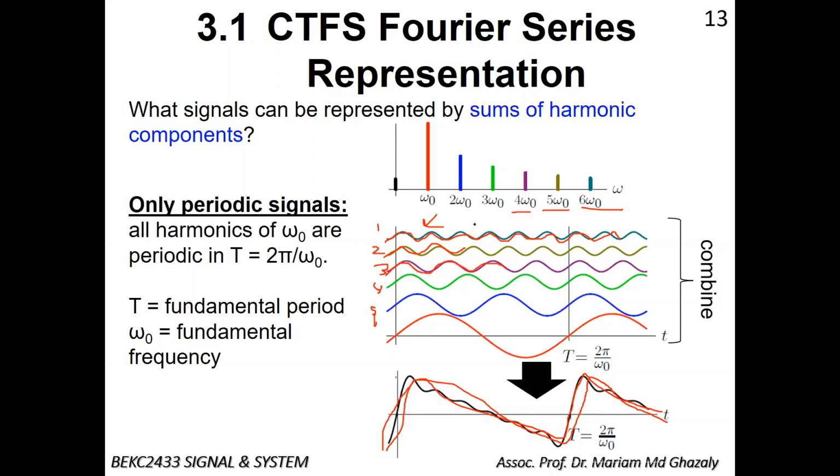So if you have the final waveform as below here, the Fourier series representation of this waveform is indicated by this Fourier sum of harmonic components. You may see a few waveform indications here. It means you have the DC term, the first harmonic, second harmonic, and so on.